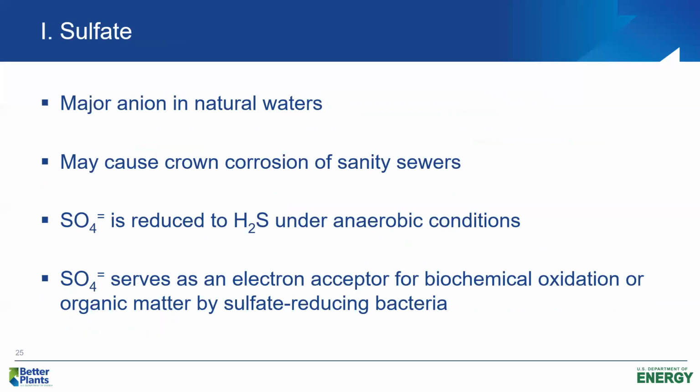Sulfate is another constituent dissolved in wastewater that we need to be concerned about. In the raw wastewater under anaerobic conditions, as the sewage flows through the sewer line, biochemical reactions start to take place. The oxygen is used up, and under anaerobic septic conditions, the sulfate will be used as an electron acceptor by the facultative bacteria. The oxygen will be stripped off the sulfate, and the sulfate will be converted to hydrogen sulfide gas. The gas will come out of solution and enter the headspace.